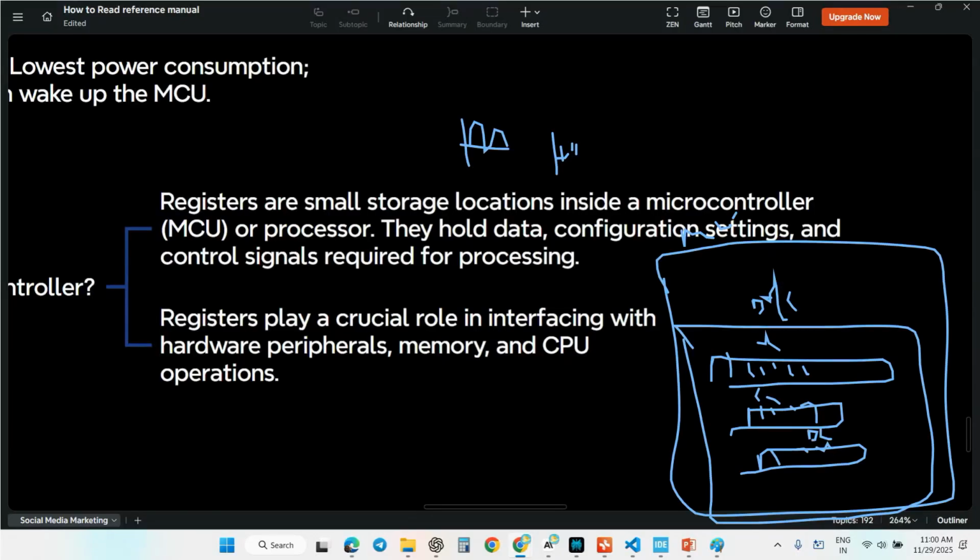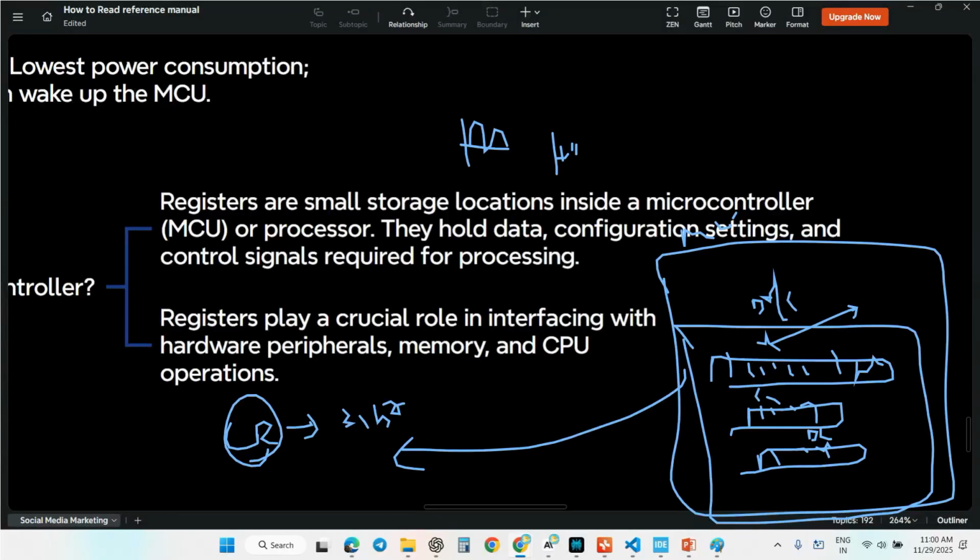If you are using only one ADON bit, it takes the CR register. The processor takes this complete CR register, the complete 32 bits, and processes it. That is what a 32-bit processor is. It takes all 32 bits, and only this ADON bit is turned on. While it is on, the complete ADC module is enabled.